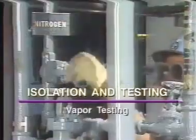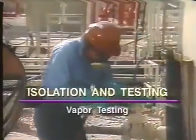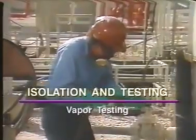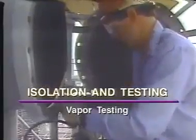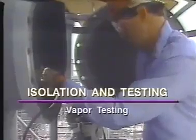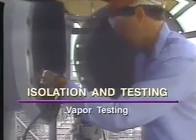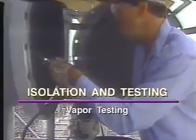Purging with inert gases and water flooding or flushing should remove all hydrocarbons from the tower. But we can't assume the tower is safe until it is actually tested. There are several different types of hydrocarbon detectors and analyzers that can detect the presence of hydrocarbons. Before anyone enters a tower, it must be tested with one of these devices.